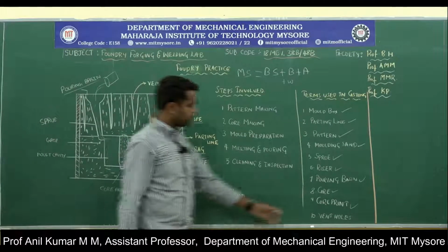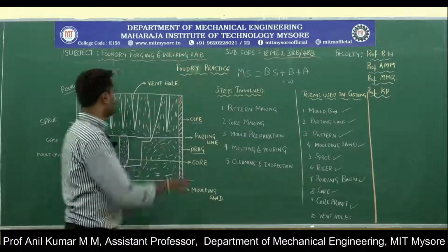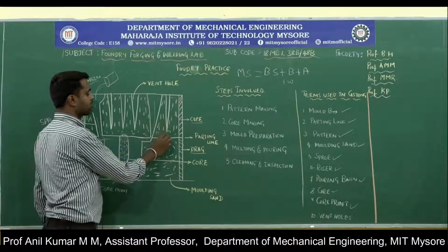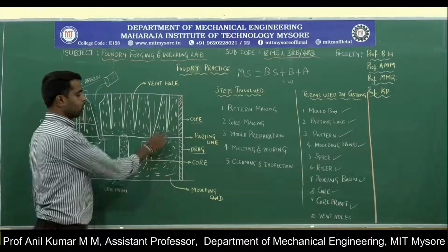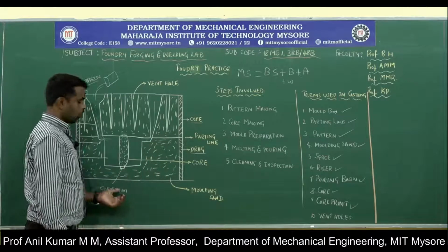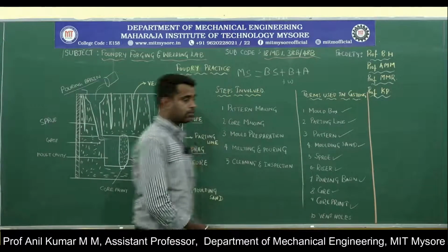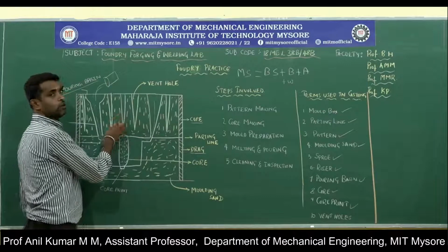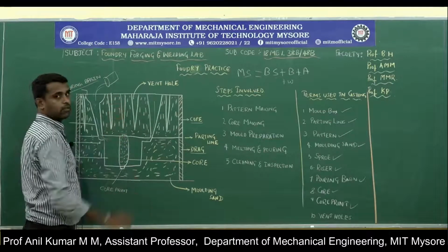Next, the vent holes. These are small holes provided in the mold for the escape of gases or air from the mold. Vent holes are small holes provided in the mold to ease the escape of gases and air from the mold.